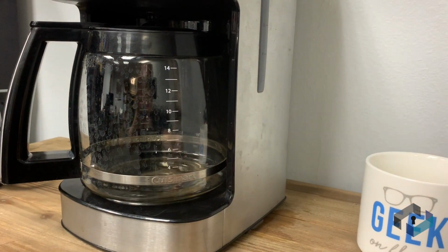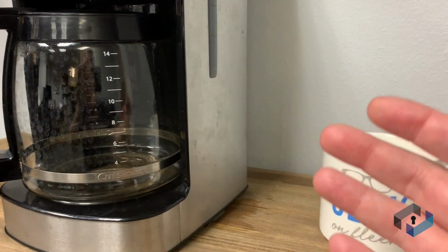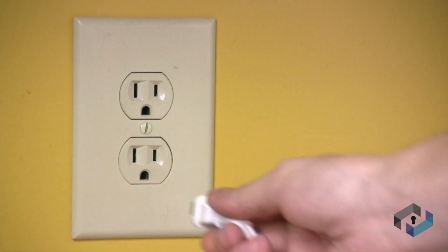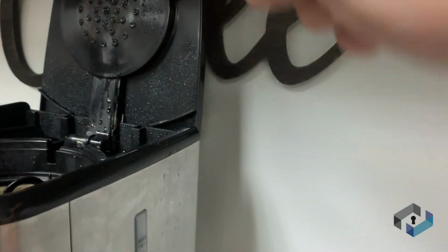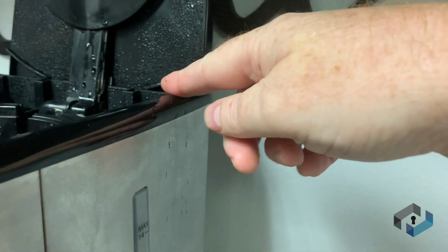Severity-wise, if that water overflows, now if it's just sanitation and it's messy, you clean it up, that's one part. But think about it, this is a coffee pot that you've plugged into the wall, so now we have electricity and water together. Somebody might get hurt. So I rank this higher. Again, whatever your own thought process is behind how you rank it, you're going to want to come at this consistently as you rank each of your failure modes.